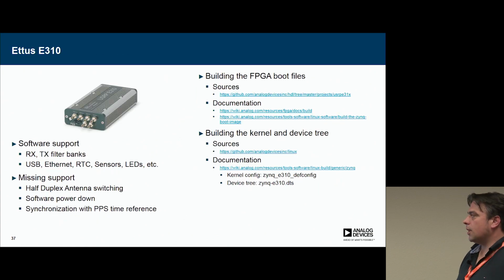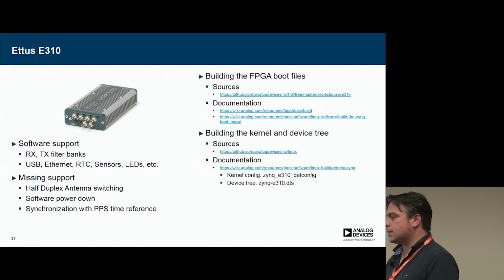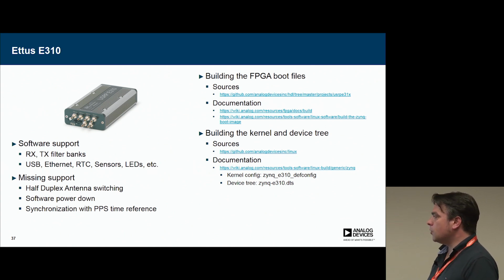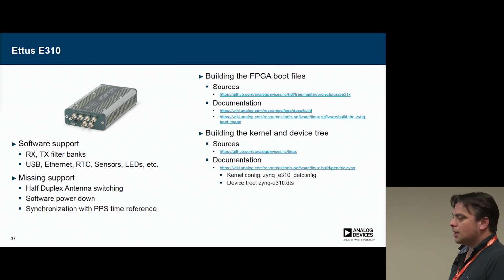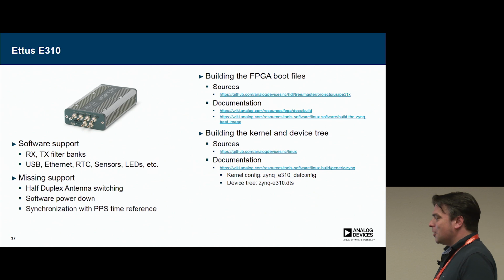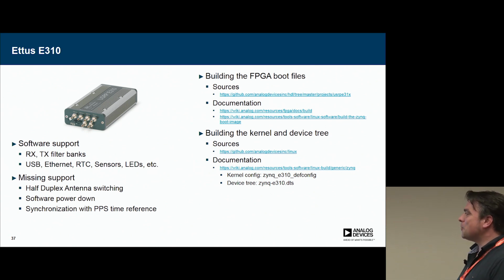Also, we added support for the Ettus E310. What's supported is the RX and TX filter banks and switches, USB, Ethernet, real-time clock, all this stuff. What's currently missing is soft power down, because it's a bit complicated to actually use it the way it is implemented in hardware on the E310.